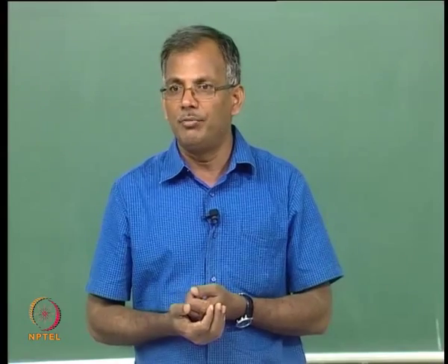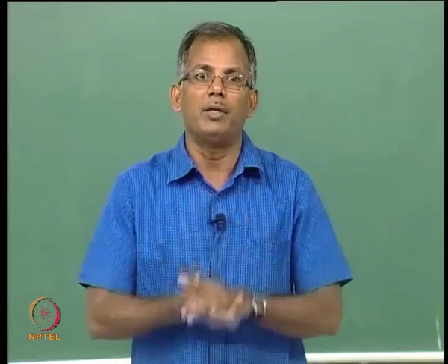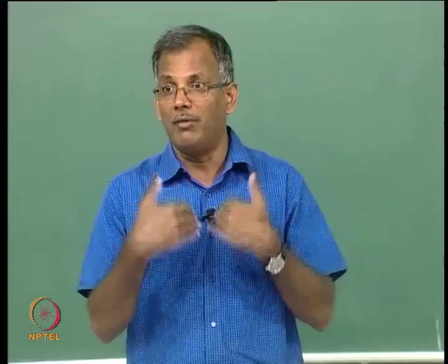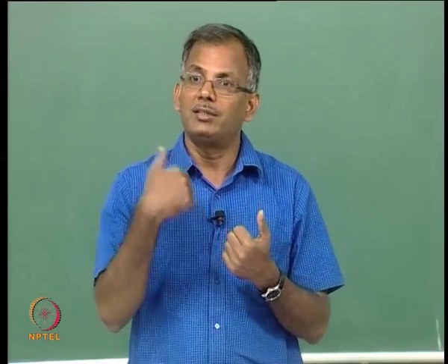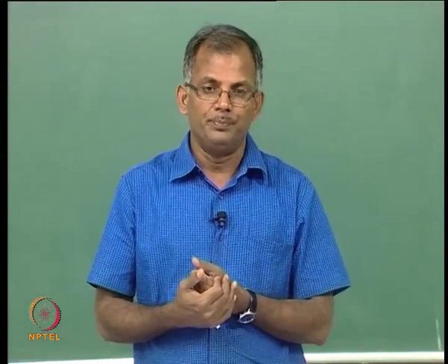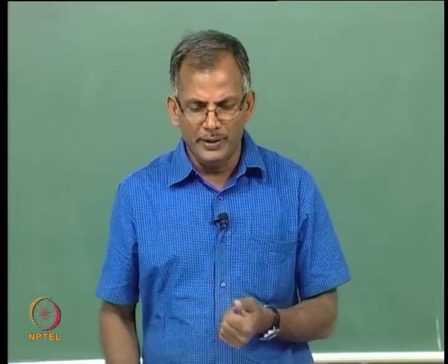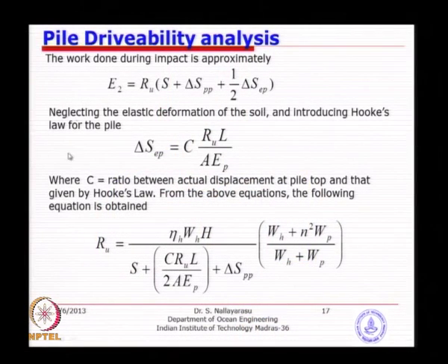If it is early refusal because the soil is too hard compared to what you understood, or if it is too soft, or the incorrect selection of hammer could put you into a lot of trouble. So, that is why this analysis, being so approximate, is normally not used, because the approximations that you make have a higher end effect. That is why dynamic formulas are not recommended for offshore pile driving.